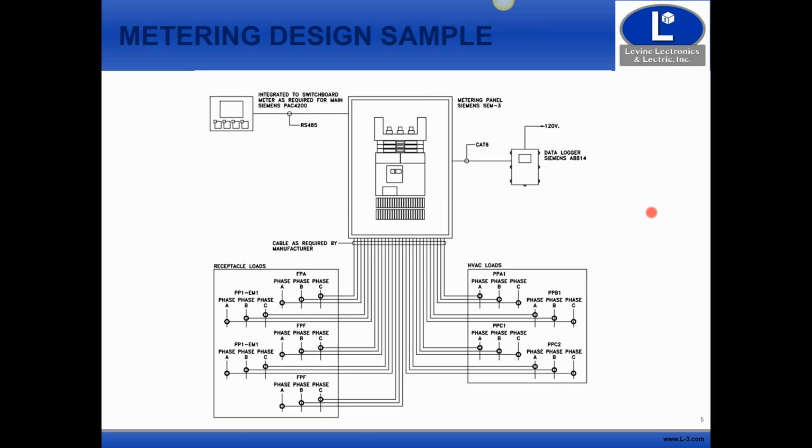Okay, so this is one way that I've seen it portrayed on drawings. I've yet to see a system like this installed. It's very cumbersome, if you ask me, trying to get it there, and the contractor's got a lot of conduit that they're going to have to run, and then you run into CT cable lengths, and how you're going to run those and make sure they're not too long. So all these are issues that we've got to address.